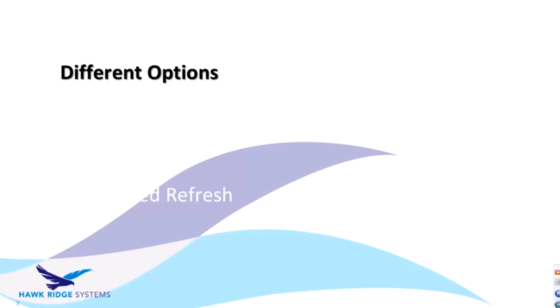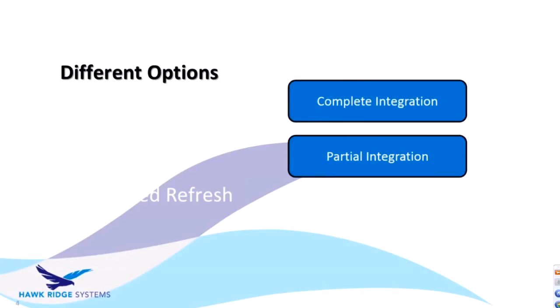So some of the different options, there's actually just two main options, the complete integration using the toolbox in Enterprise PDM or partial integration. So, the toolbox, the custom parts includes a library of standardized components that users can insert into their assemblies. EPDM can manage the toolbox so that all the data management operations are performed automatically. EPDM manages both the part files and the toolbox folder. Once it's configured, users can then just point to the toolbox in the vault and use the toolbox as normally